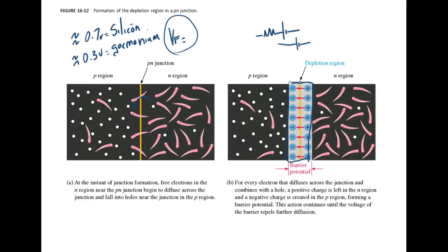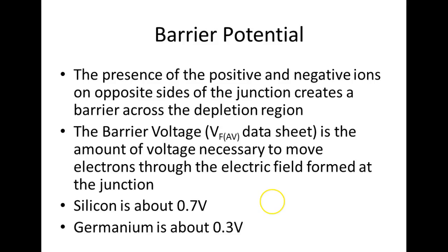So if you got a good old ohm meter, if you put it on about the R times 100 scale, what's going to happen is very interesting. Let's typically show it. So barrier potential. Everybody understand what we call the barrier potential? Everybody okay? All right. Now what becomes very, very neat is when we put a voltage across this P-N junction.